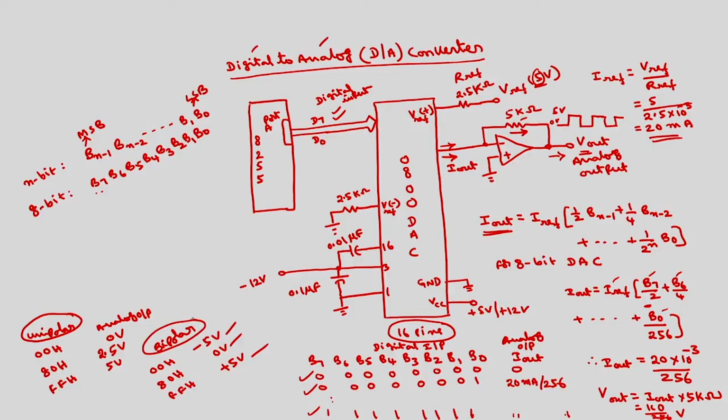Here if I want to generate 0 volts, 5 volts, I will take the reference voltage as 5 volts. So if I send here all zeros over this data bus, you will get 0 volts on this line. You call some delay, then again you send FFH, you will get 5 volts. So I have to program this port A whose address is FCH and the control register address is FFH.